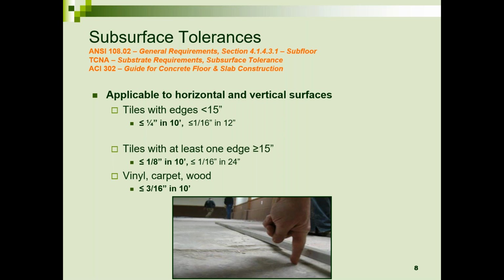And if you're on smaller tiles, the requirement is 1/4 inch in 10 feet. Those are the standards. And in the case of working with vinyl carpet or wood, you've got no greater than 3/16 inch in 10 feet.